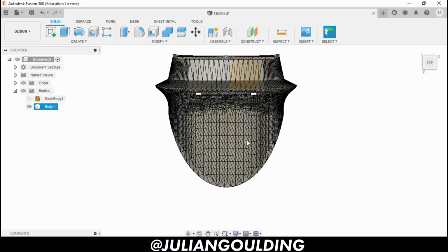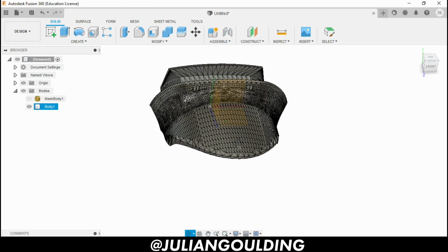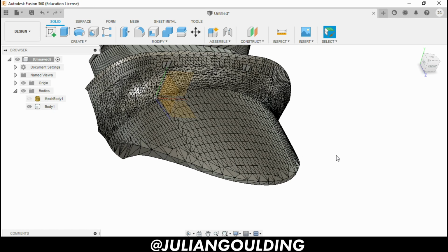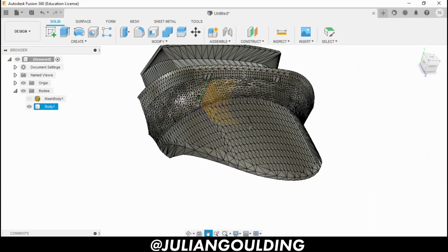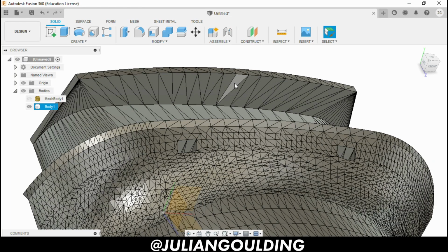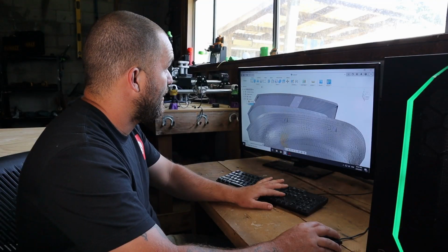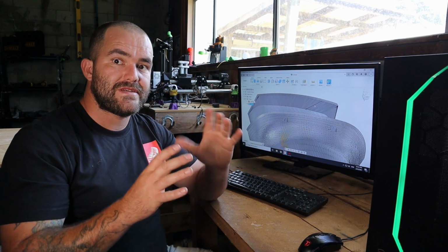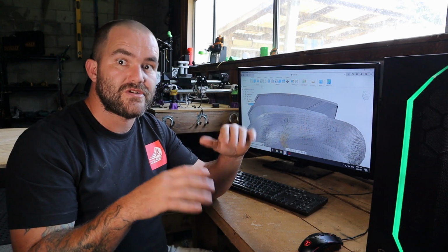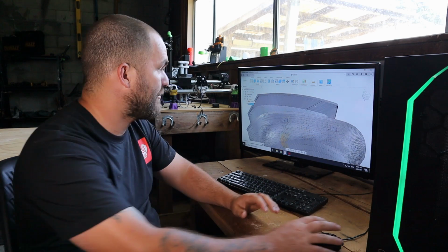You'll notice obviously that your bRep is made up of thousands of little faces. If we want to now convert those faces into surfaces that you are more used to, we need to do it now before we turn our timeline back on. There's two ways that you can do this, the simplest of which is you can just click on a face, bang delete, and what it'll do is it'll just patch that face and try to merge it with the ones next to it. A little bit tedious, but if you've only got certain pieces that you want to turn into a flat surface, this is quite a handy tip.